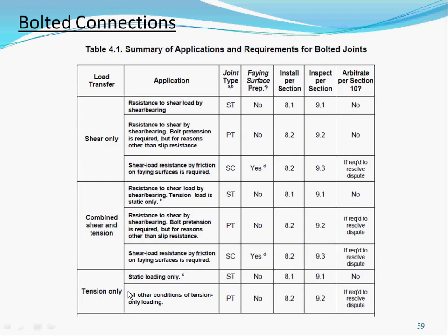Okay, so that's tension. What about this one? Shear. That's mostly shear. So for shear, we have three options: shear resisted by shear, or shear resisted by bearing. Both require pretension, but for reasons other than slip critical. We fall under here.